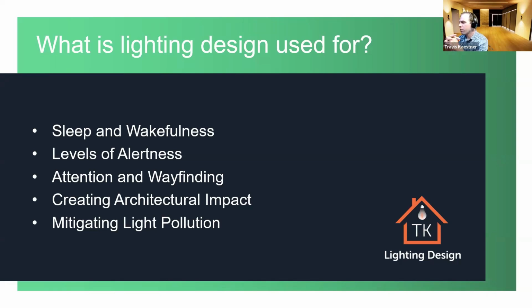And then mitigating light pollution, having controls when you're lighting your facade, doing the same thing, doing the layers of light. You want that to be all shut off in the evening or dimmed down, and not have just glare bombs shining into everybody's house or floodlights shining into your neighbor's driveway. That's what lighting designers do. They look at all that. They look at the photometrics, where it's going to be, and then help specify all that.